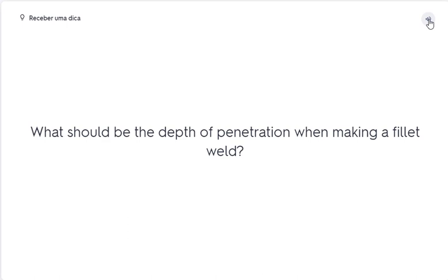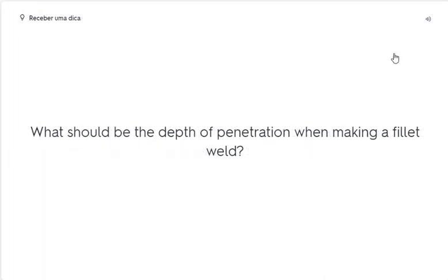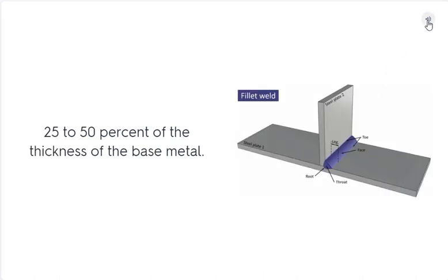What should be the depth of penetration when making a fillet weld? 25 to 50% of the thickness of the base metal.